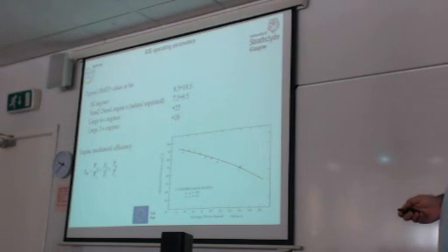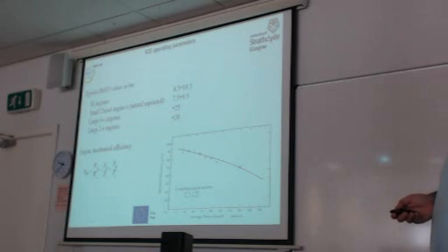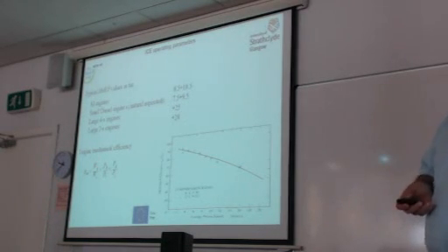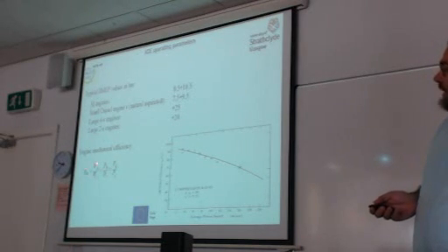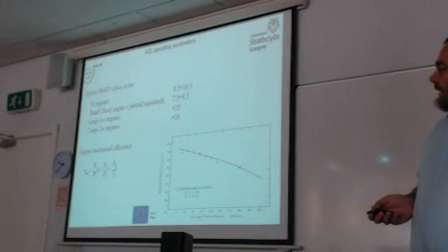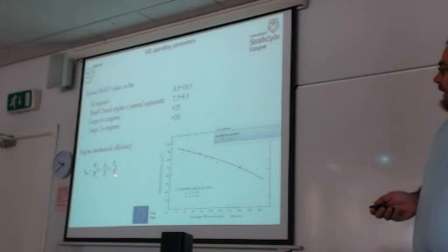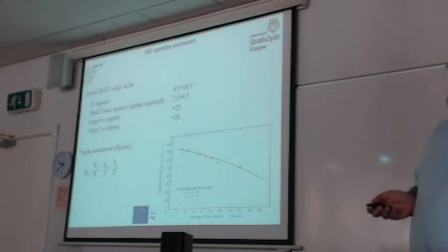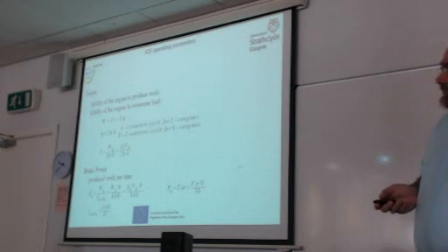Then typical values for marine engines. For the large two-stroke engines, we have numbers of 19 to 20 bar. And for large marine four-stroke engines, we have numbers for brake mean effective pressure up to 25 bars. And then we can also define the mechanical efficiency, which characterizes the mechanical losses. We know that mechanical efficiency is the useful power over the given power. In the case of an engine, it is the brake power over the indicated power. The larger the engine is, the larger is the mechanical efficiency. So the slow speed engines exhibit the highest mechanical efficiency.